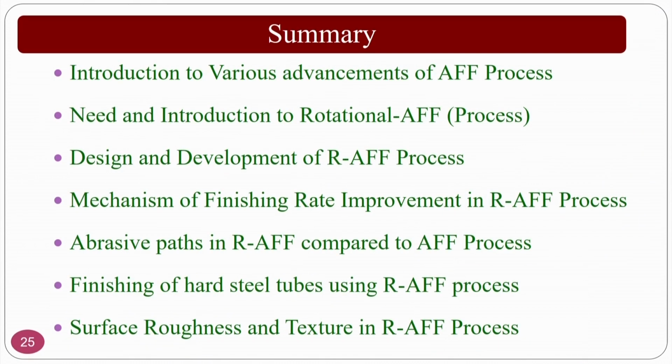Okay. Summary of this class: what we have done is we have seen the introduction to various advancements, that is spiral polishing process, drill bit guided abrasive flow finishing process, and centrifugal force assisted abrasive flow finishing process, and then we moved on to the rotational abrasive flow finishing process. The need is in the above processes. In the above processes, the problem is that the medium is given active motion, which may not be carried to the workpiece finishing region.